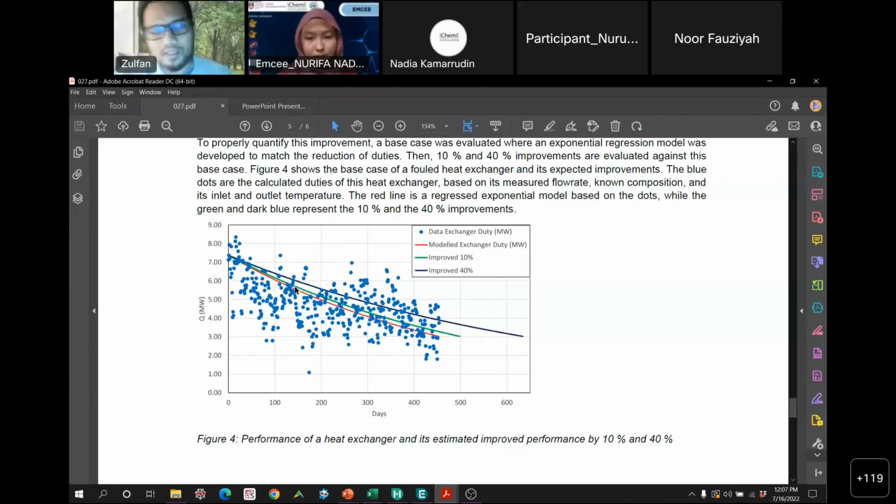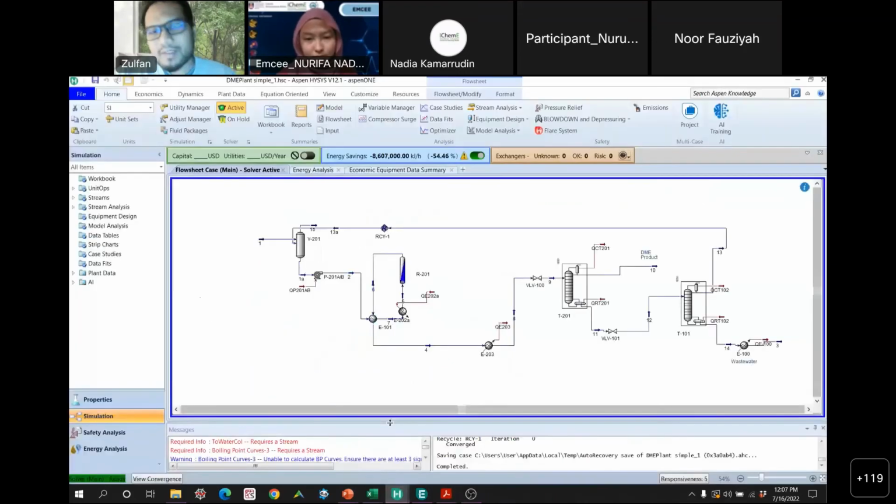Because in the plants here, for example, sometimes we have the flow rate over there, and then there's no flow rate anywhere else, and then there's temperature over here, and temperature over there, but we don't know what the temperature in between is. But they do have some temperature over here, so you need to get that calculation complete, and then you have to make a sound assumption, something that makes sense, so that you can have a feeling whether your data is correct, and that it represents the current situation.